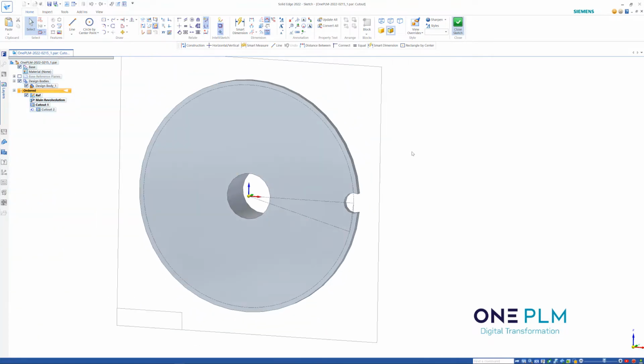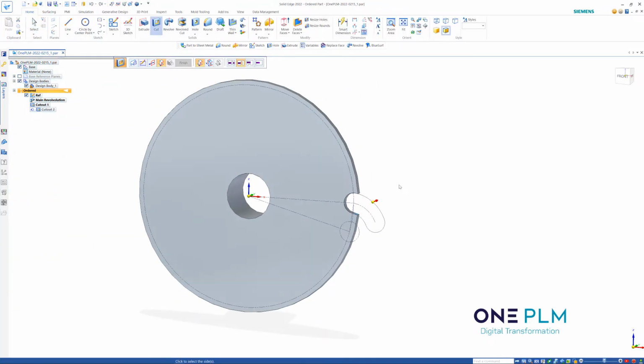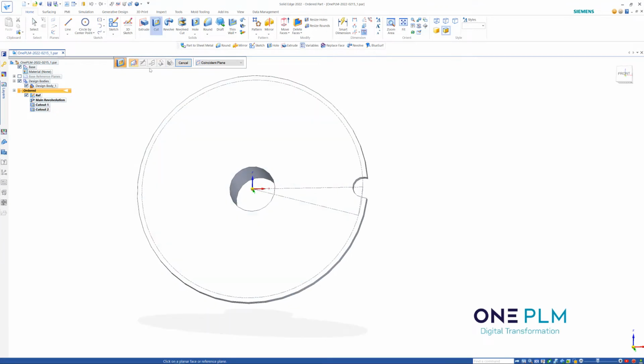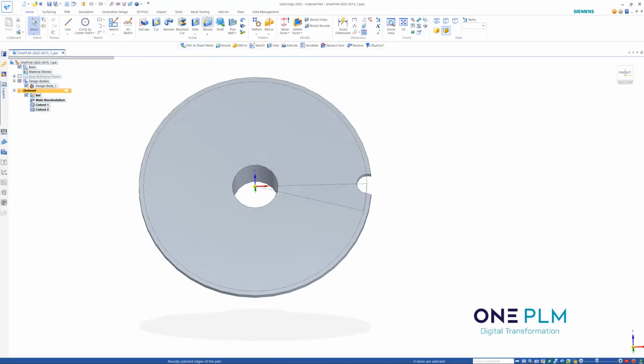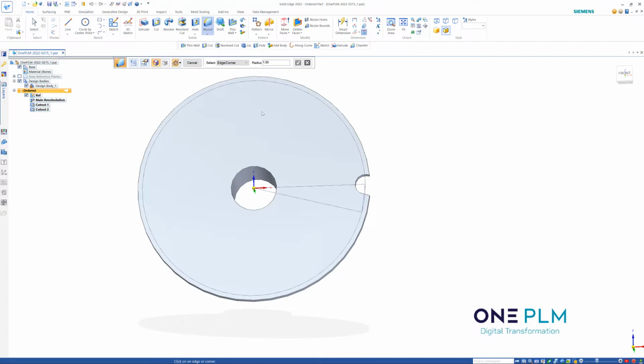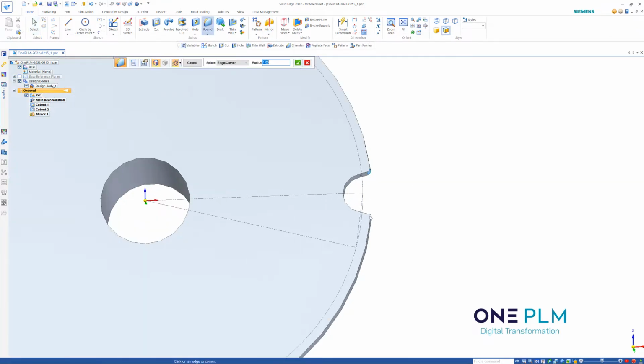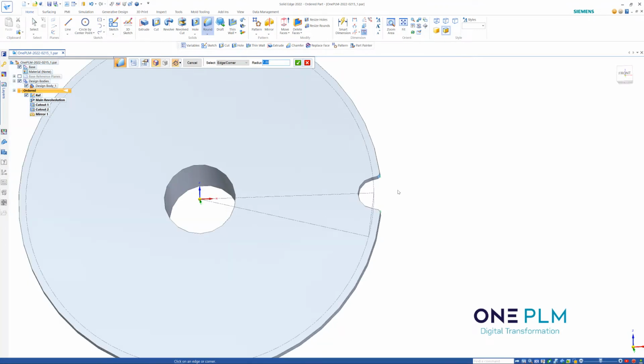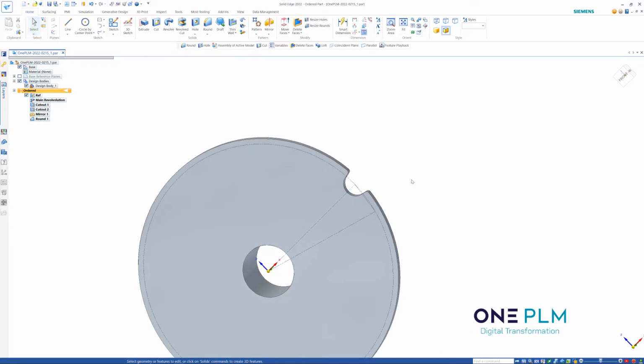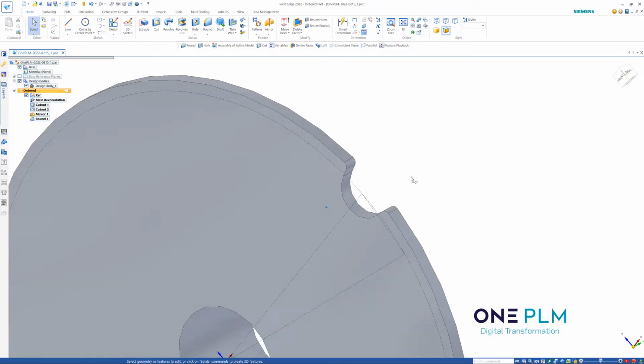We can then close that sketch, cut out on there. We can then go and add, actually I'm going to add the round afterwards. We can then use the mirror command to go and mirror that cutout using the XY plane in my instance. So we end up creating that mirror up there. And then we can do a round to these two edges. So on these, just going to stick with a small 1mm round on there. And that has got our profile looking okay on there, nice and smooth once we look at that.